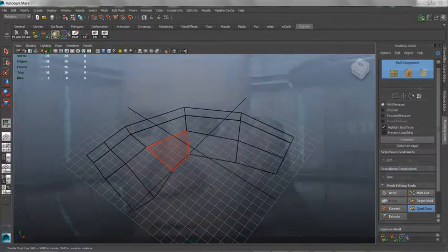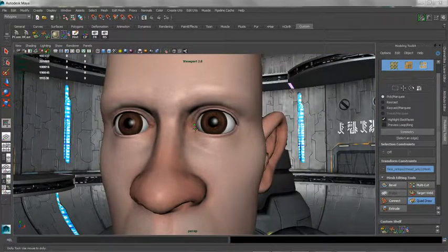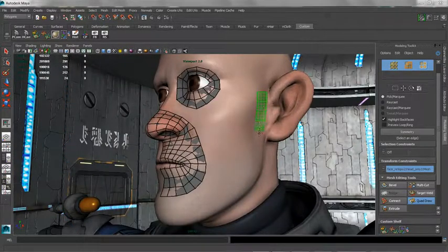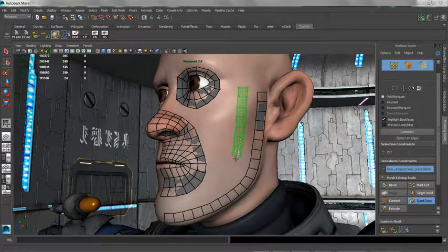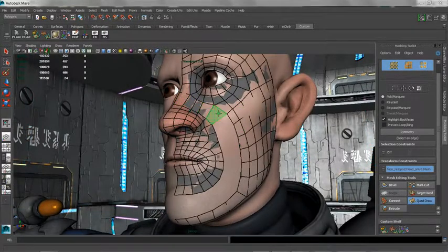The same process works over top of a model, enabling a very simple and effective way to make an animation-ready mesh in minutes. With Quad Draw, you can retopologize your mesh directly in Maya. This feature is particularly useful for resurfacing imported higher resolution meshes from other sources, including 3D scan data. Another feature within Quad Draw is polygon strips. Just simply click and drag to create strips of quad polygons. This tool presents an excellent way to quickly build geometry over an existing surface for a retopology workflow.